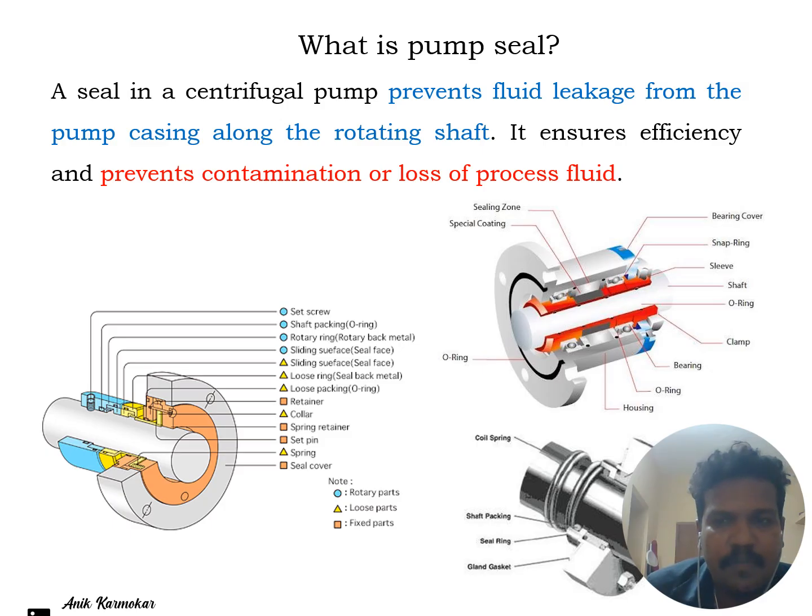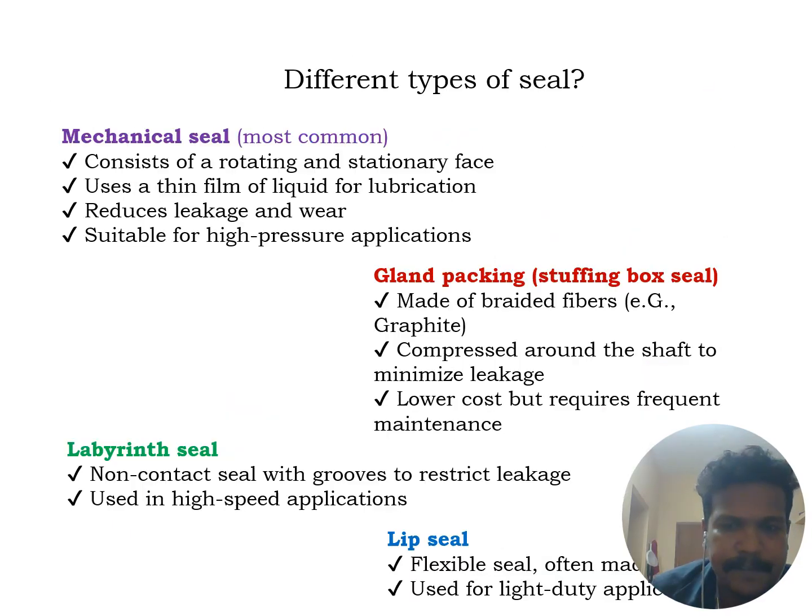The shaft connects the motor to the impeller, and water flows through the space between the impeller and the volute casing. There is a small gap between the shaft and volute casing which can cause water leakage. To prevent this, the gap is properly sealed using different types of sealing materials. The seal is installed in the space between the shaft surface and the hole surface in the casing. It connects moving and non-moving parts, so it wears out quickly due to friction.